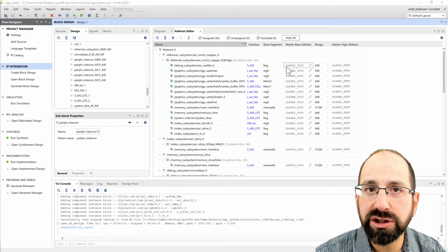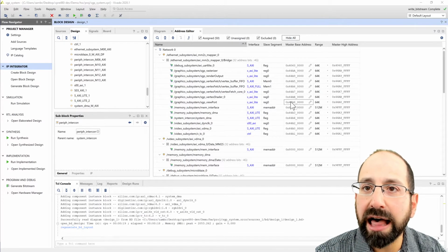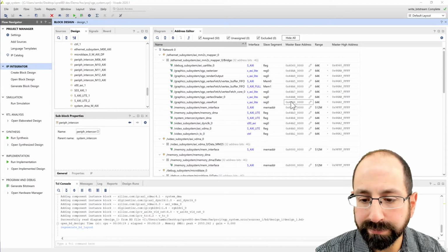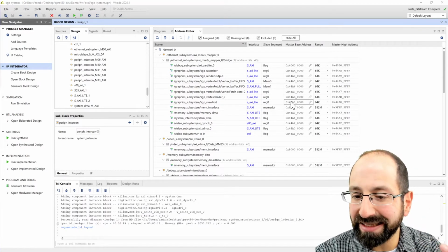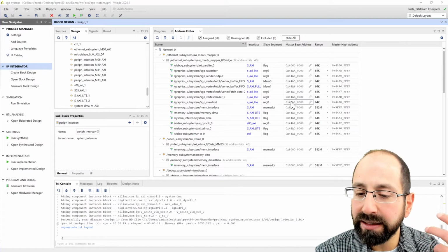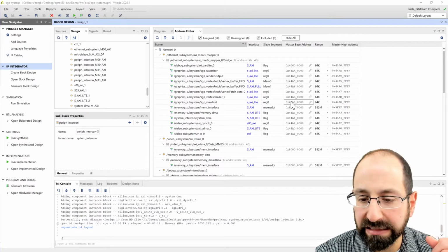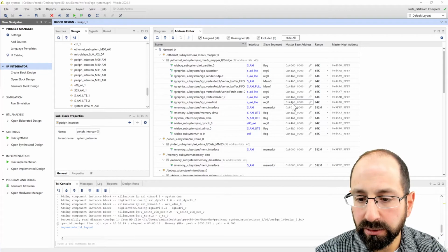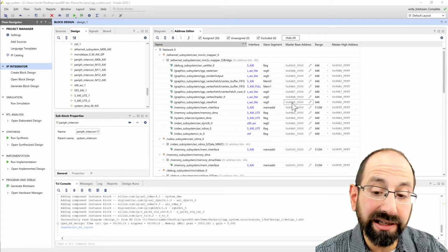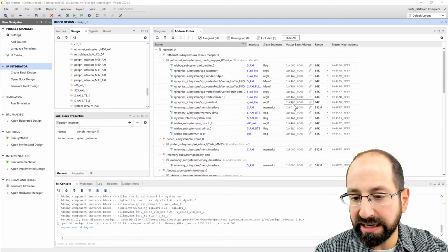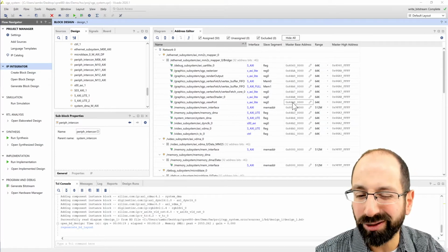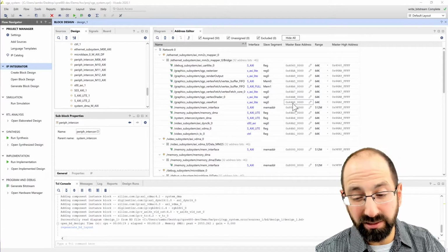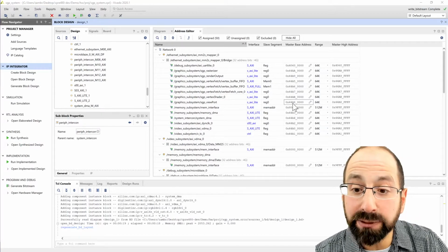I want to potentially send a value to my viewport core. Somewhere in the viewport core, there are those AXI Lite registers, and those are going to be configured as an offset from the base address. What those offsets are is something you get to determine, both in the header or the .c file for the driver, as well as which registers you physically put this various information in the core itself. I set some for you to start with. You're probably okay just sticking with those, but that's what's happening here.